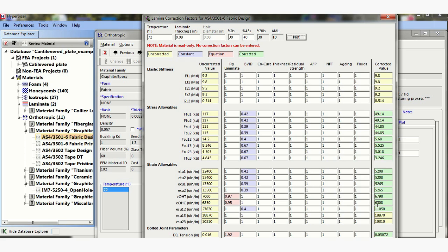So this is why a lot of people that are new to the topic, they go do some analysis and they use these pristine values and have no understanding of certification of aeroplanes and what we're supposed to do. And I've been on many programs where I've come along a year after the start and a bunch of stress engineers are using these pristine allowables. Well, unfortunately that's not correct. And even for secondary structures, we need to take into account all of these manufacturing processes and make corrections.